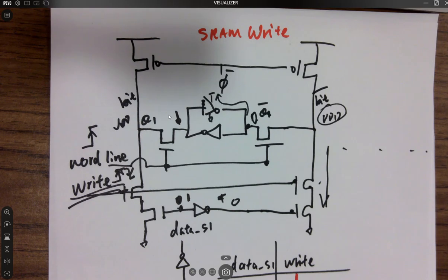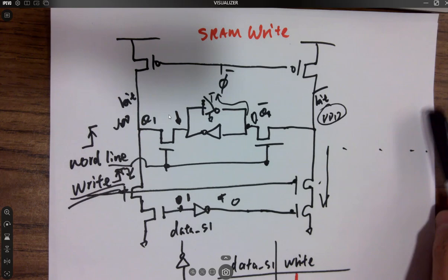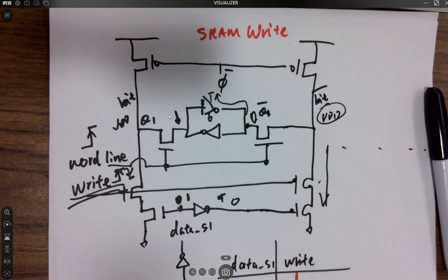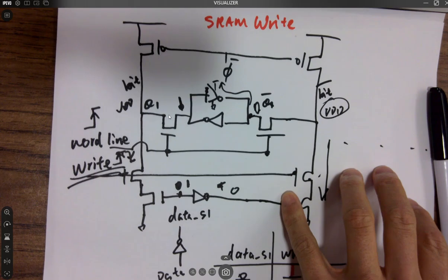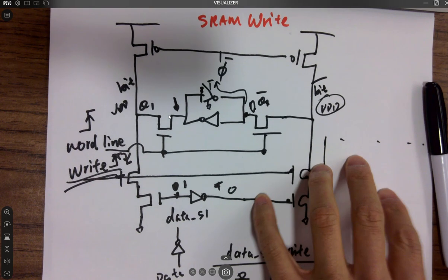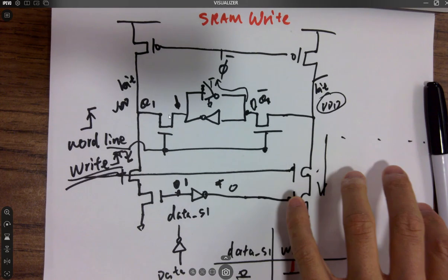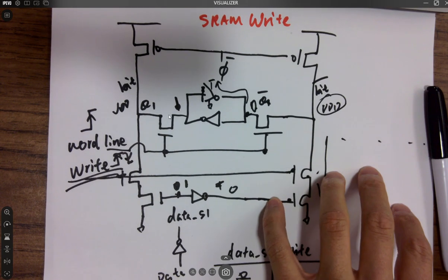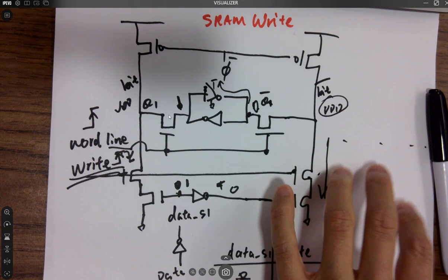Okay, so in that case, if you are designing a microcontroller and you are not using a memory compiler, which is a specific software provided by the foundry, running on a server in Linux or some other kind of machine, you just describe the memory by its behavior in Verilog and synthesize it. Eventually, it's going to give you different flops based on latches or SRAMs. And that will be huge.